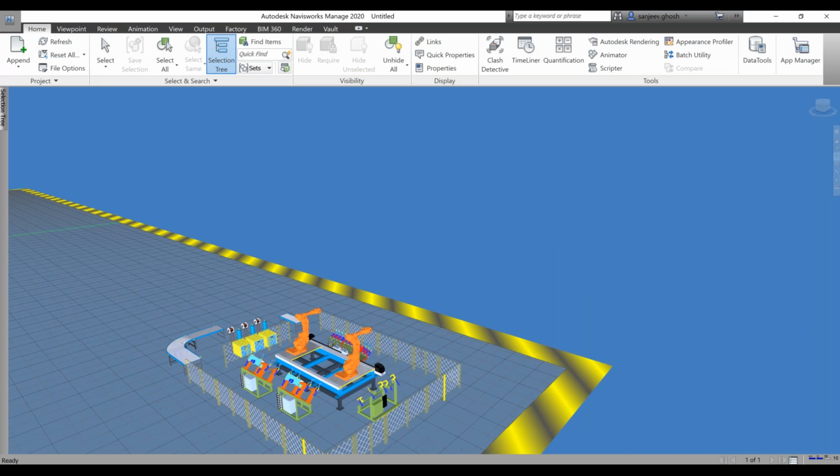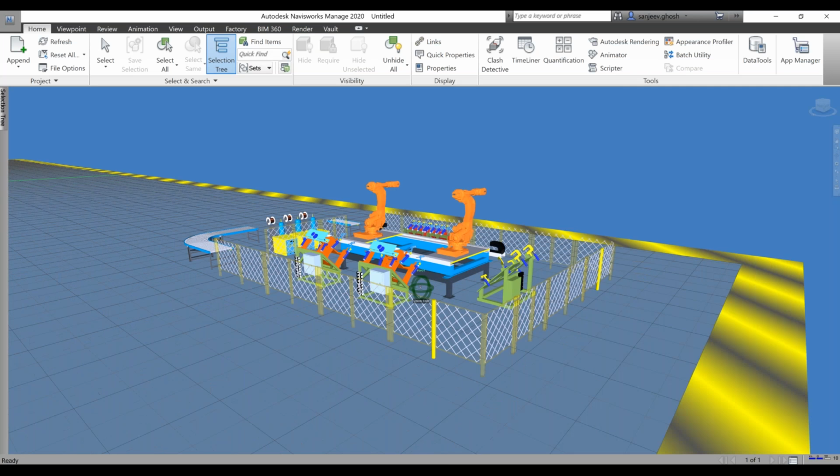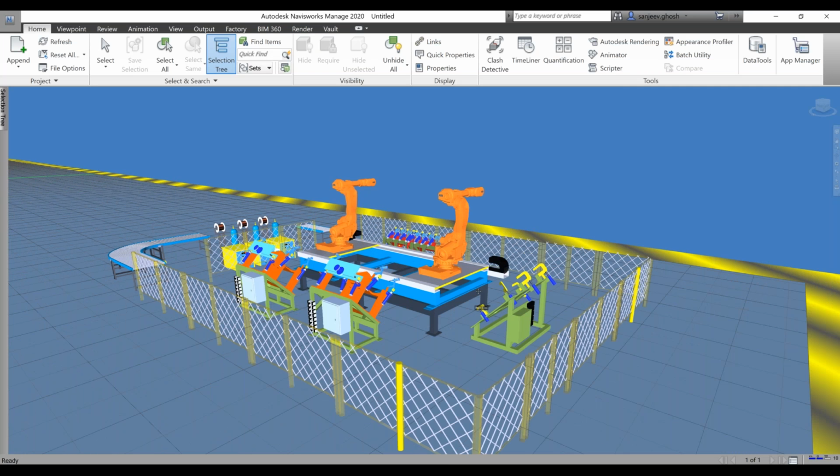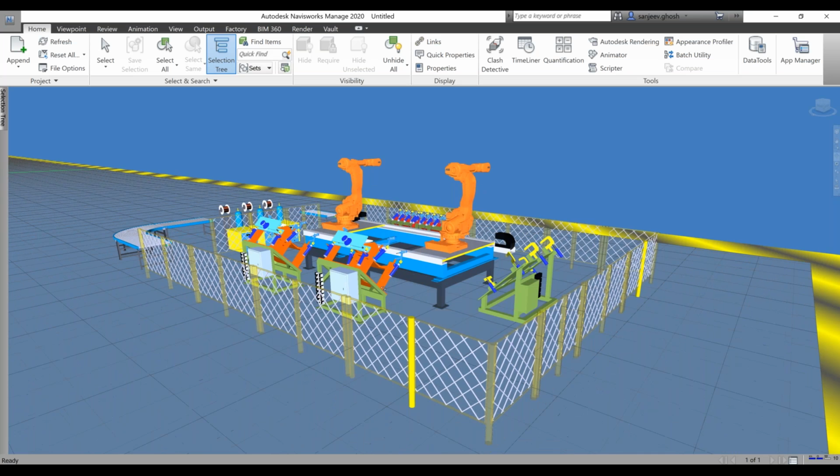And if I want to check for a clash between, for example, HVAC or refrigeration lines or ductwork and the structural part, and these are being done by two different contractors, how do I do that? That is something that I can do in Navisworks. So this is a factory owner's tool for reviewing inputs from various stakeholders.